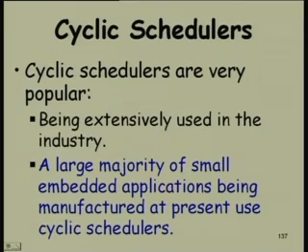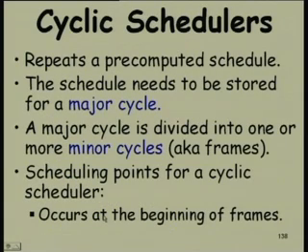Let us see the cyclic scheduler, where no timer setting will be necessary. It is extensively used; for almost any small real time development you want to do, you will use a cyclic scheduler. A large majority of small embedded applications use these. Here, unlike the table driven scheduler, we do not store the entire LCM period and keep repeating.